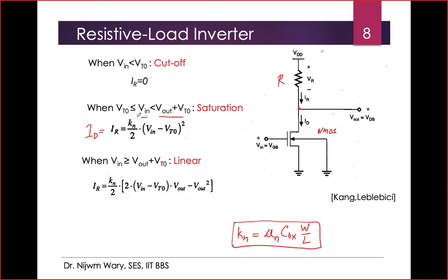Anyway, this is the MOSFET equation, and here we are considering the effect of lambda as 0, and ignoring the short channel effect, just to simplify the analysis. Lambda is not 0, but we are considering it so, so that we can easily simplify things. We'll see why we are doing it later on, but at this point, to simplify the analysis, we are putting it as 0.